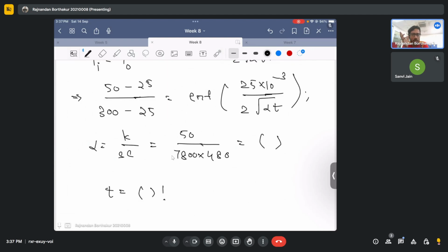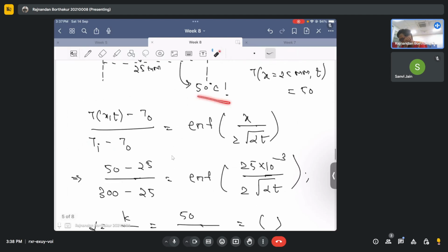Maybe because most of the physics of heat transfer in transient conduction can be modeled as a lump body. And then we also saw the semi-infinite solid, where we saw that you can use something known as the similarity solution to come out with the temperature field as something like this. And we saw the reason why you use the similarity solution: typically because I know how my length scale is related to the time scale of the problem, at least by an order of magnitude analysis.